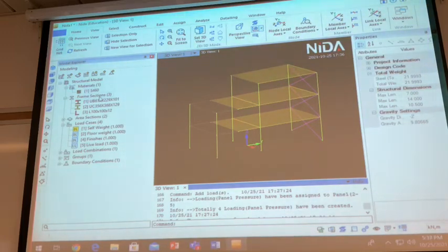When you erase more degrees of freedom, it means that you impose more restraint. Then it will go from the determinate structure to the indeterminate structure. That depends how many restraints you impose in the structure. But so far, we haven't imposed any boundary condition, so this structure looks like a vehicle that can move. So we should impose the restraint or boundary condition.